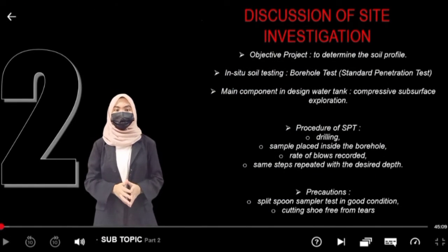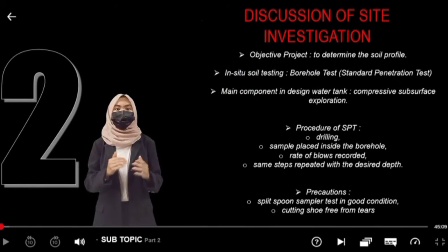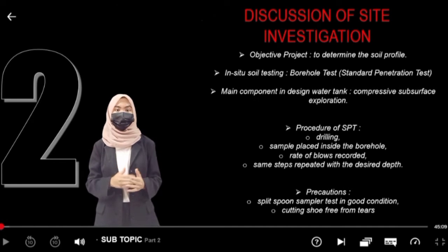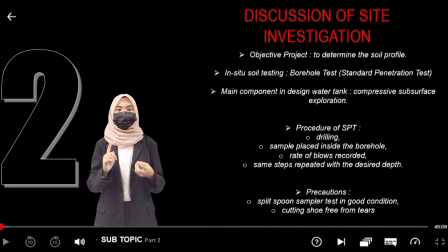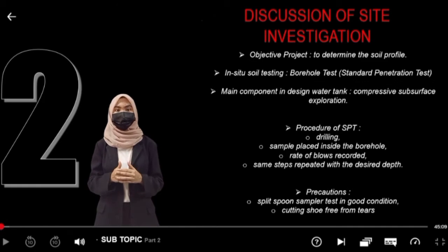Next is the discussion on site investigation of boreholes. The in-situ soil testing, which is the standard penetration test, was conducted. So, the objective of this mini project is to determine the soil profile by plotting a graph of SPT N versus test depth, as well as evaluate the compressive strength of the soil based on the correlation between standard penetration test and also shear strength parameter.